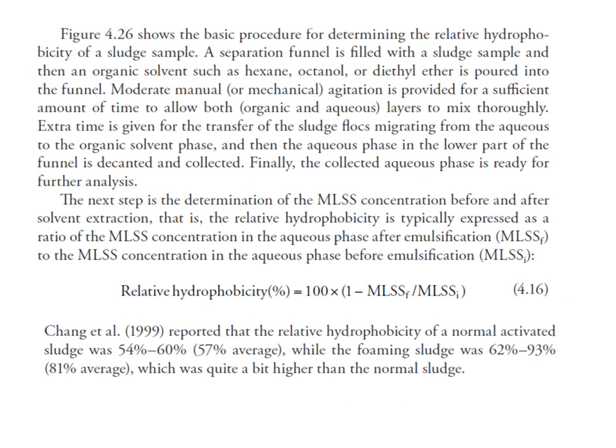In the next slide, you'll see the procedures for determining the relative hydrophobicity of a sludge sample, and that's basically the way of doing this solvent extraction. Organic solvents such as hexane, octanol, or dimethyl ether are used for this extraction.